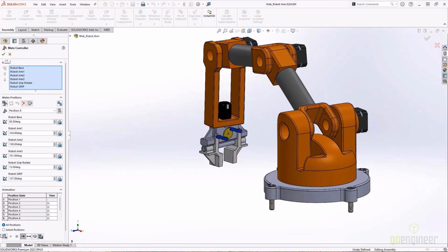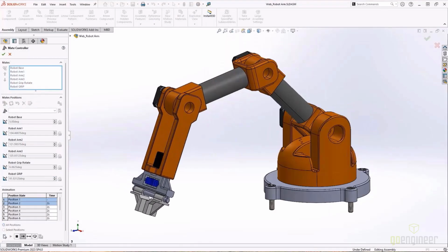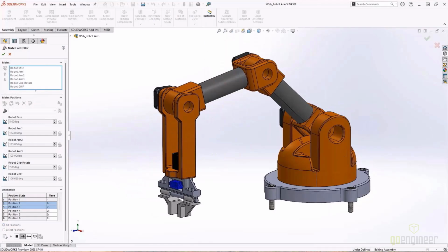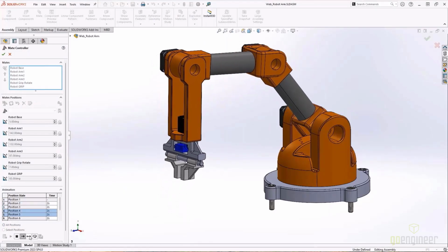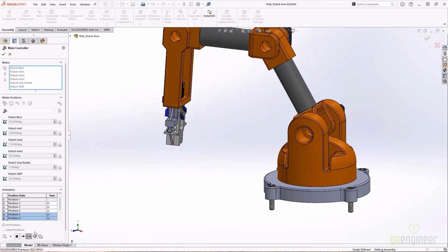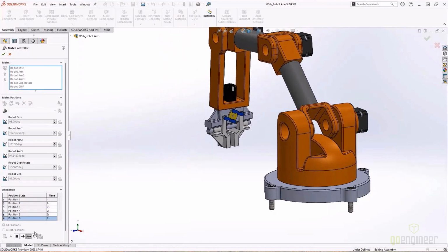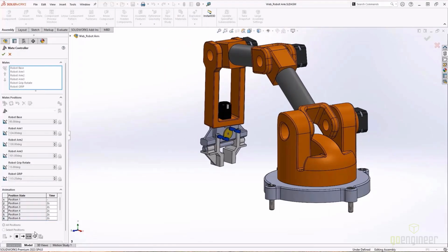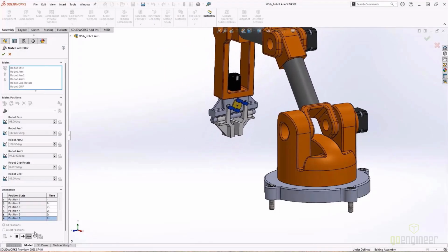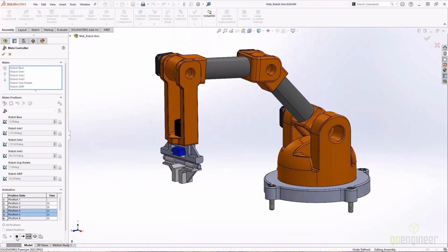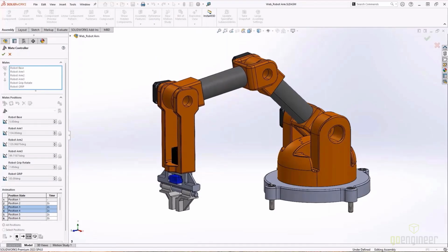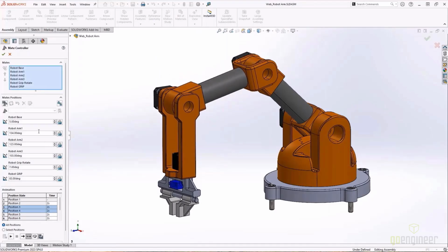All right, so then down at the bottom left, we're going to hit the little calculate button. And all it's doing is going through position 1 to 2, 2 to 3, 3 to 4. You can kind of see it going on the little animation. Drop that down and you'll see it start to open back up. I can hit the reciprocate button. So then it's actually doing this in reverse now. So it can act like it's going to go over and grab another one, except of course I would have wanted to open up before I closed it. And that's pretty much it.